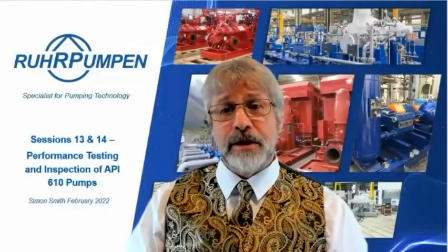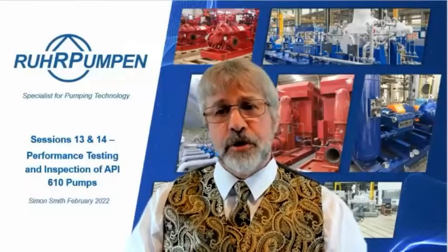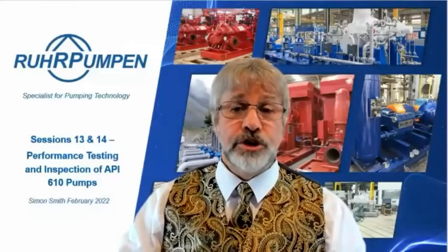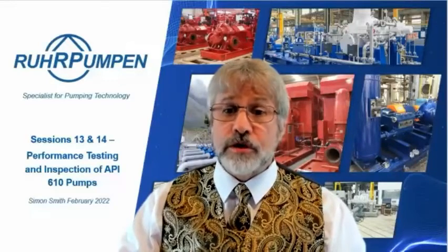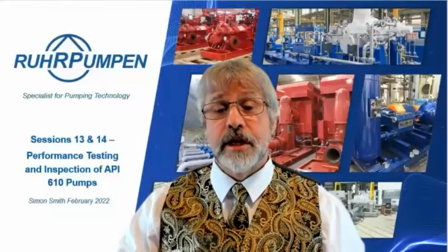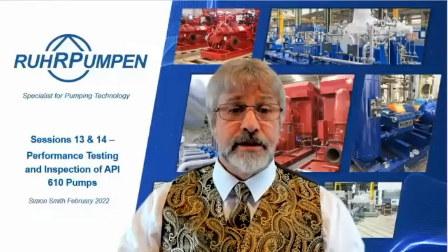But do remember as well, you're testing this pump on water, not on hydrocarbons. So are you really accurately testing the seal flush plan if you do it? A normal performance test would just use probably water from a hose connected to the seal flush piping for doing the performance test. You're not actually doing a test of the seal and sealing system.